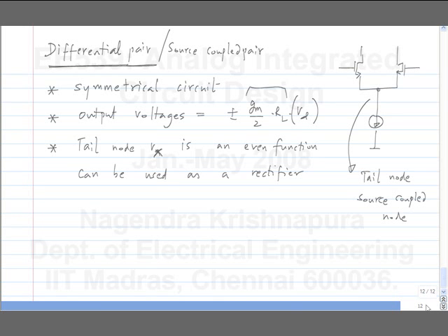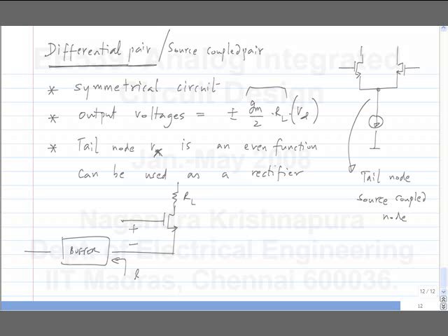See, the gain from here to here is GmRL, right? So if I do have an ideal voltage buffer with Rout equals 0, then whatever I apply here also appears here. Okay? But what is the impedance looking this way? 1 by Gm. What is the impedance looking in this way when you use a real source follower? Also 1 by Gm. Okay?